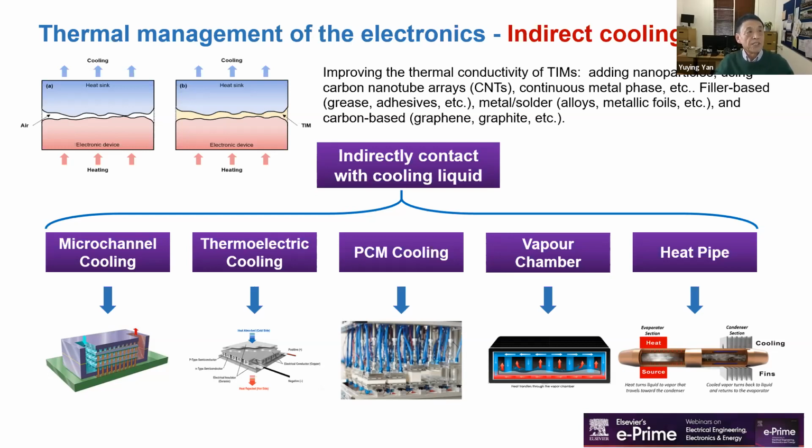First, it was mentioned that the air gap between the electric device and the heat sink surface has a very significant impact on the heat removal process. Therefore, the thermal interface material, called TIM, should be used. The thermal conductivity of TIM can be improved. The current conductivity is low, so that improvement could be like adding nanoparticles, using carbon nanotubes and so on.